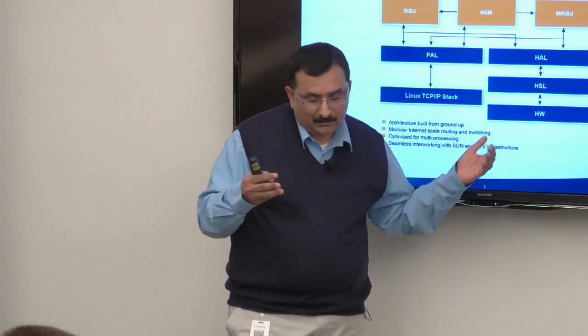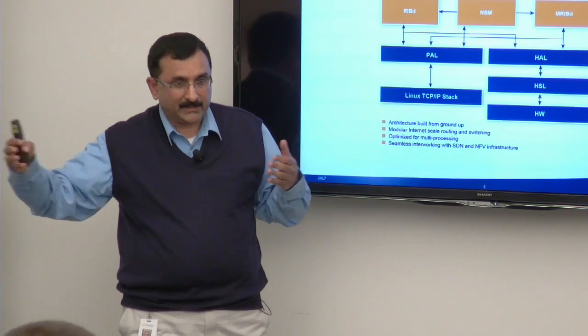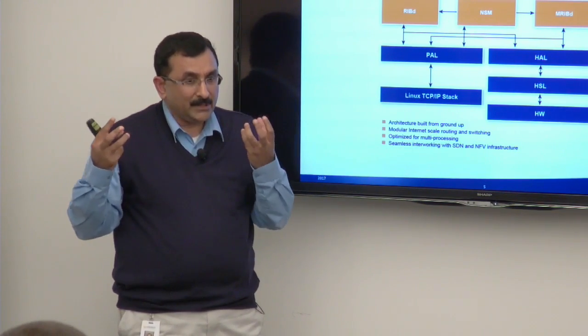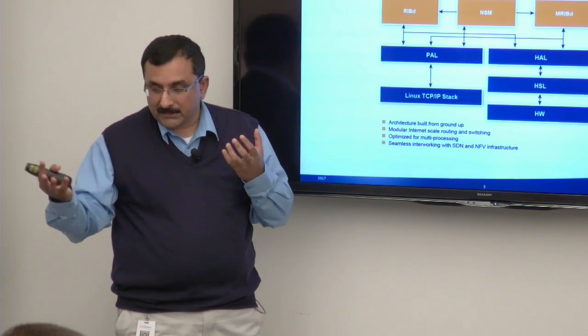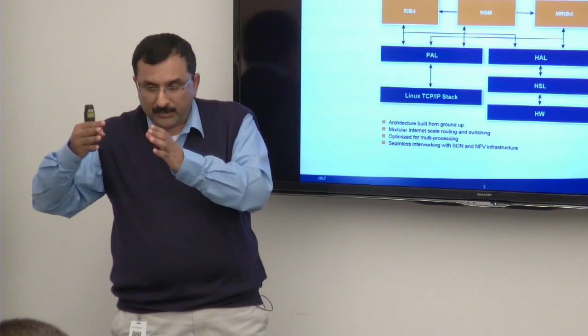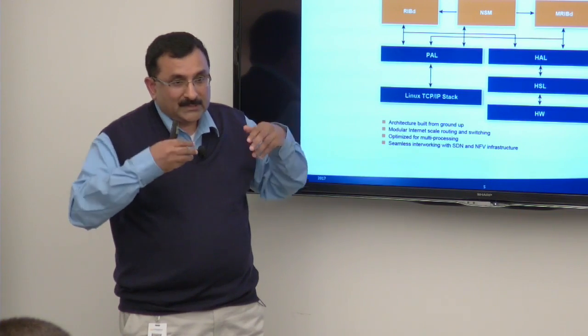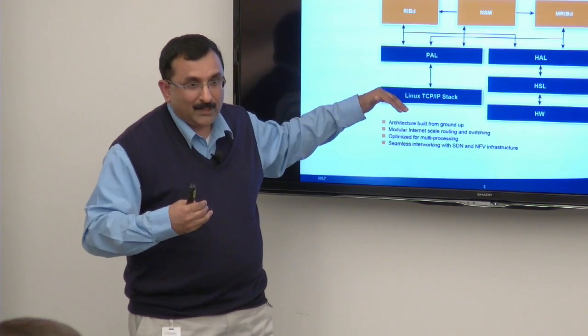So if I have the talent to understand that telemetry data, I can understand where my potential bottleneck or issues are at. Exactly. So what will happen is, in certain chipsets, right? If you look at something like a Tomahawk versus a DNX chip, like Qumran, right? The traffic engineering would be different, right? Because it's meant for edge aggregation. So in edge aggregation, there's a lot of grooming that happens. So if you look at that versus a spine switch, right? It'll be completely different. So the statistics that you get would be dependent on what the underlying layer is.